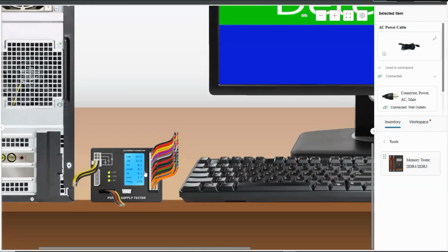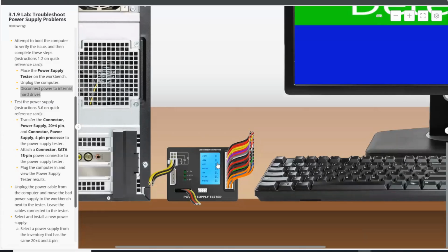If your test doesn't return the voltage that you have here, that is the indication of an issue with this power supply. Especially the symbol LL, that means it's low. As you see, everything is LL. It keeps changing, so it's never equal. That is the indication of a bad power supply. So that's how you know, everything is L.